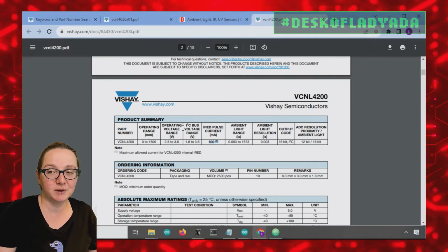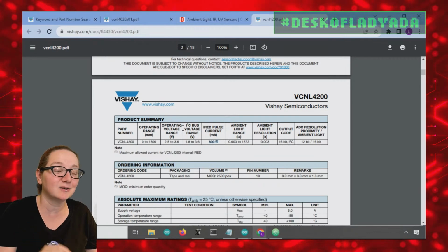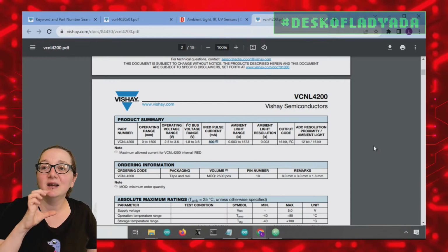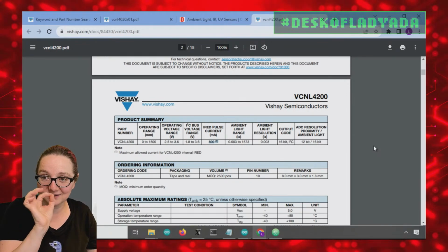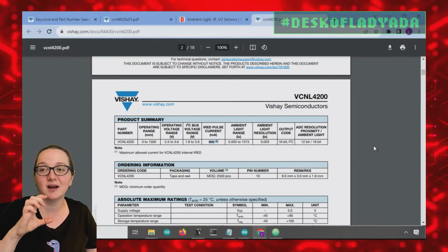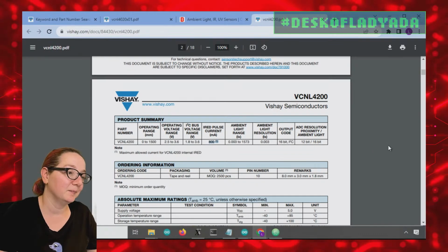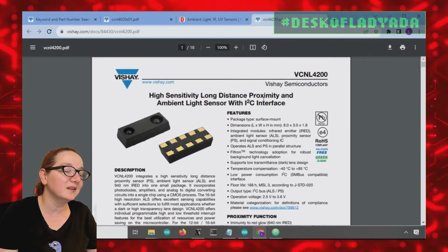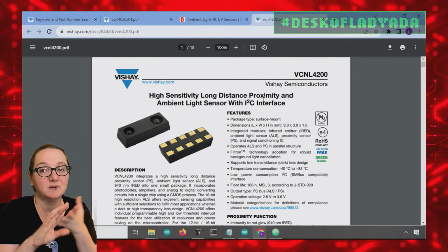So you'll need to make sure that you have a huge capacitor on the board where you're using the sensor, because your power supply can't necessarily supply 800 milliamps, but maybe for that microsecond or less, if your capacitor is like 100 or 200 microfarads, you might be able to buffer that current to get the data out and back. So this is a very interesting chip. I think this is, again, inexpensive, will do the job for basic distance proximity measurements.